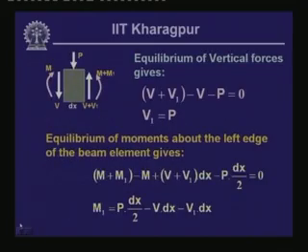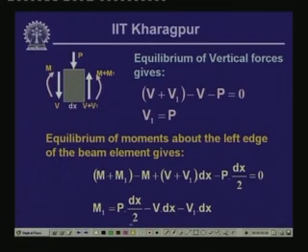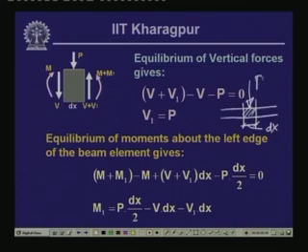Now, let us look into the case where the beam is subjected to a concentrated load. Now, as we have shown earlier, we take out a small segment of the beam, the length of which is dx, and over this dx a concentrated force or a concentrated load P is acting on the beam. Now, here you note that in the previous case we had the change of V over the length dx as V plus dV, here we have noted it as V plus V1.